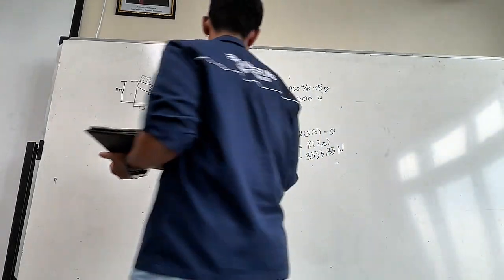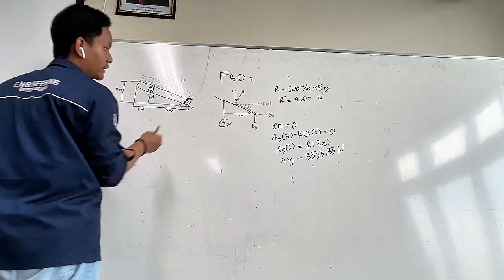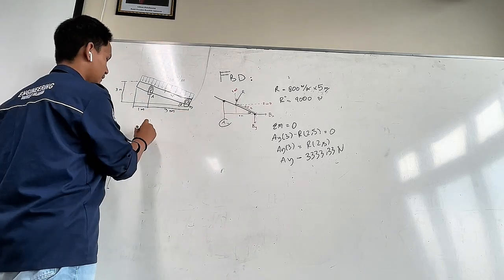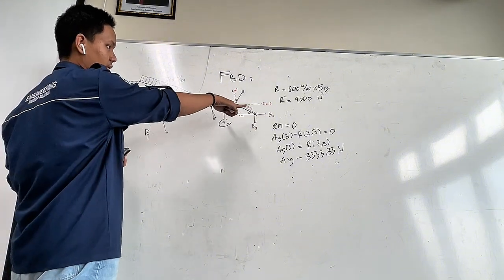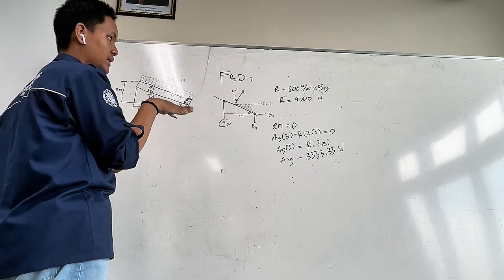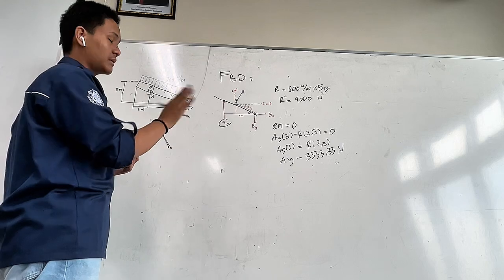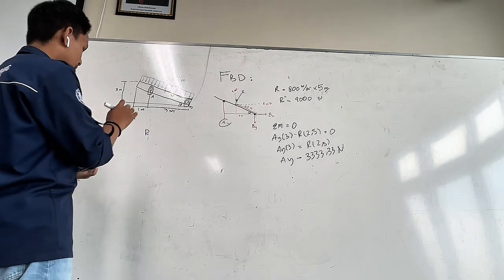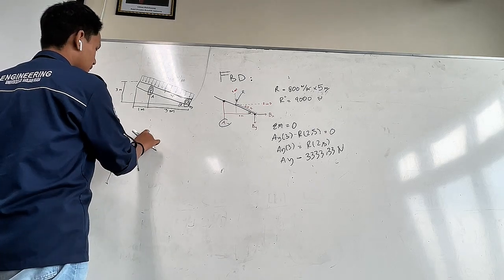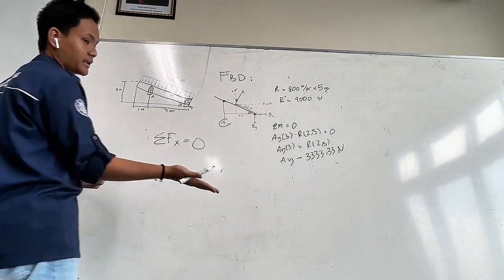Okay, so for the B part, we can analyze it from the x and y axis that I've drawn here. On the x-axis, the resultant is also acting, denoted by resultant sinus of theta, and on the y-axis, it's resultant multiplied by the cosinus of theta. We're going to find theta later on, but we can start by writing that sigma, the total force applied on axis x, is 0 because it's an equilibrium again.